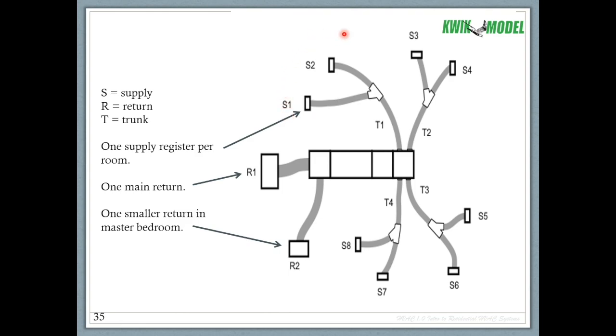Notice I don't mention what these rooms are. It doesn't really matter what these rooms are. What matters is what is the load on these rooms. The load will take into account the types of rooms that these are. If one is a kitchen, then you should have put extra load in that kitchen for the stove and the oven, what we call internal gains.